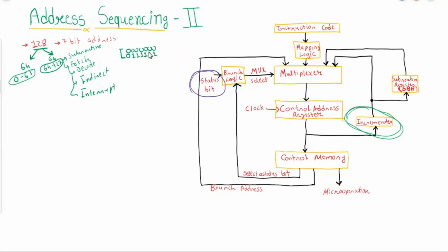Okay, so this portion will be used for instruction. Clear? Now we know that in instruction register there are 16 bit, so 12 bit will be used for, let's say, address, and 4 bit will be used for opcode.